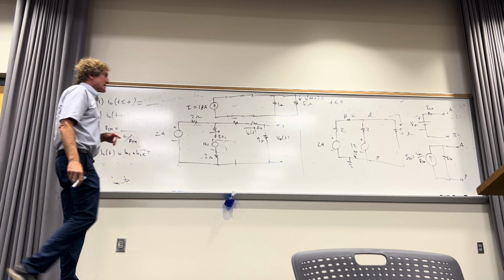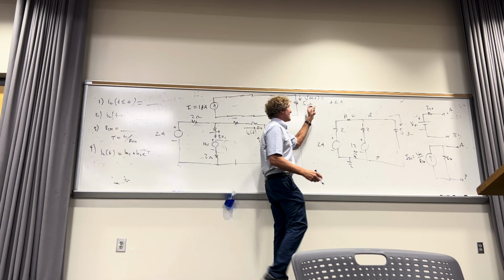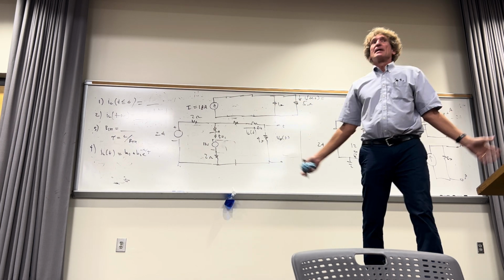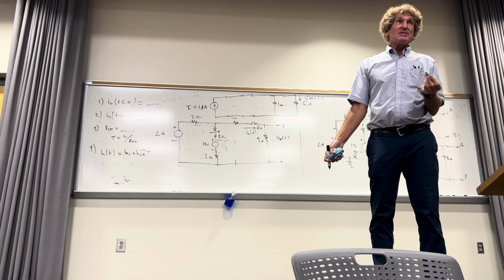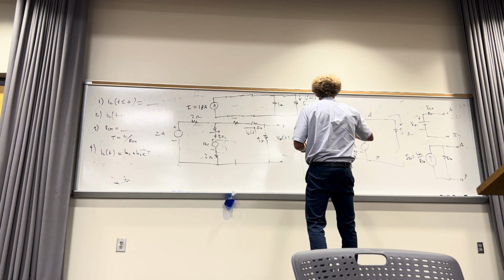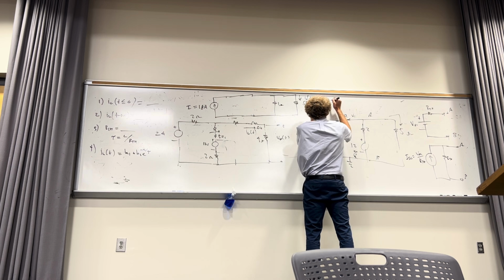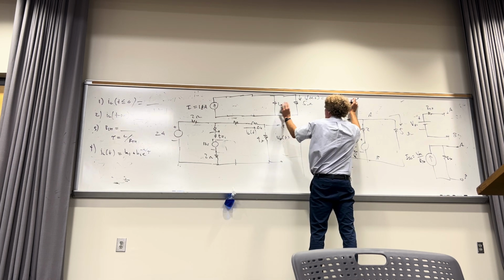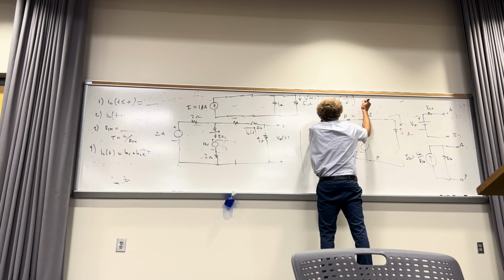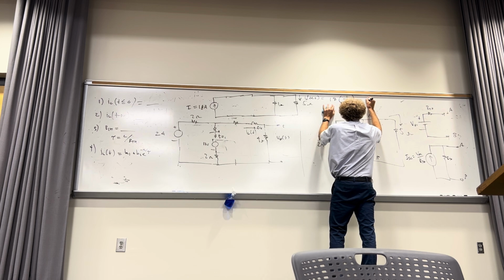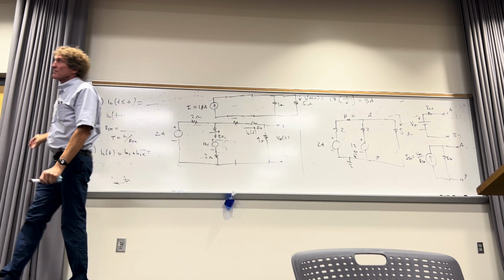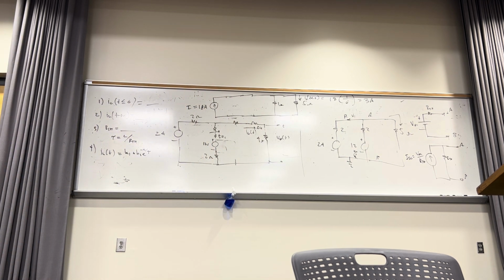Now, look at this. How do I get this current? I have 2 resistors in. I would use current division if I knew the current going through them. Do I? Yes. So what is this current that I'm after here? Class? It's 18, right? Times the opposite resistance over the sum. Or, what is it? 3 amps. Can you all see that, class? Give me a show of hands if you can see it. I'm not trying to make light of this. I'm really trying to underscore, it's not that hard.